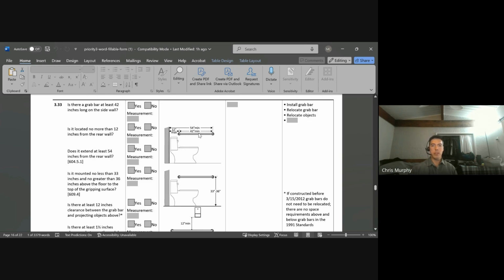If you use a 42-inch minimum grab bar, you have to be absolutely dead on the installation 12 inches from the wall right here in order to hit the endpoint over here. If you use a longer bar, a 48-inch bar, then you have more leeway. You can install the left end in the photo within 12 inches, 8 inches, 6 inches from the wall, and you're going to be fine on the other line. So that's a very easy fix or something to look out for when you're in a restroom stall.